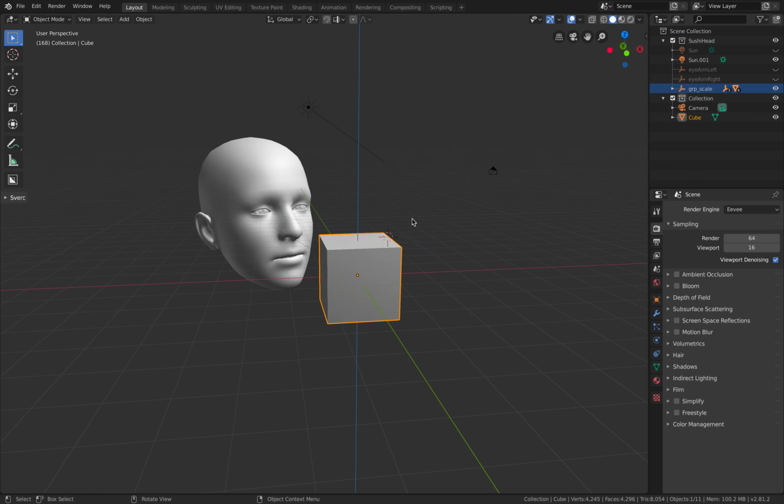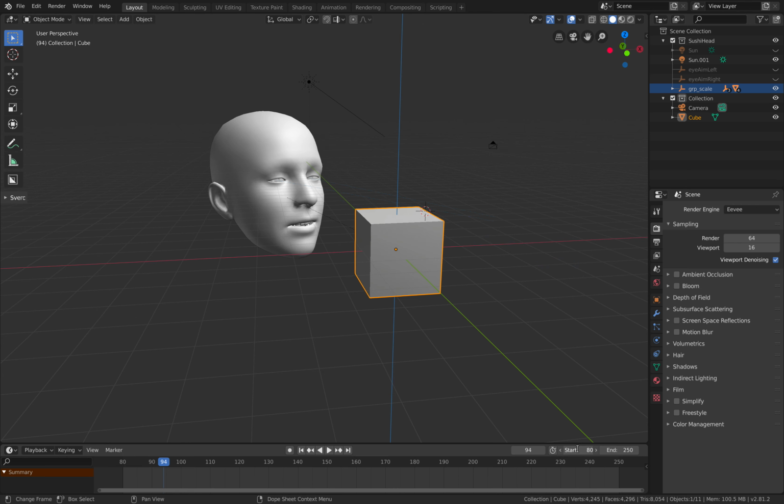Kind of like a tick to represent the time where you're in, which frame. So normally it starts at frame 1 and ends at frame 250. So if you want to see a little bit of animation, you can do that. Let's make a keyframe of this box.